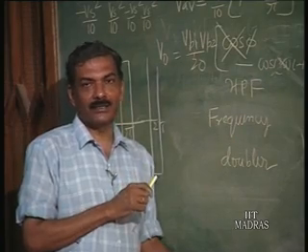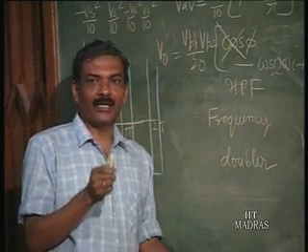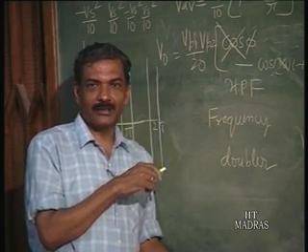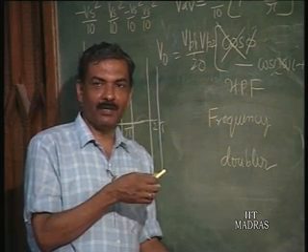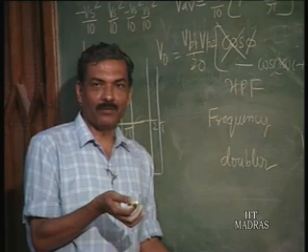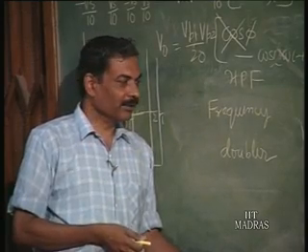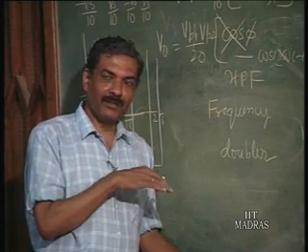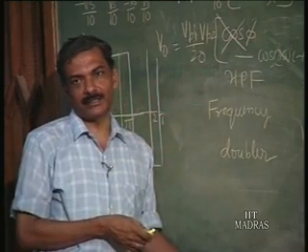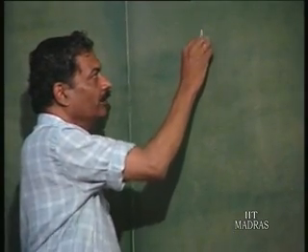If you can use it for frequency synthesis, I can get omega, 2 omega, 3 omega, etc. Then I can generate the harmonic components, and I can therefore obtain any periodic waveform using a periodic waveform as the input. A triangular waveform, for example, can be used as the input. Triangular waveform is nothing but x or t. So, using this input I can generate a sine waveform, which is going to be t minus t cubed by factorial 3, and so on. So, we can generate a periodic waveform of any shape using a triangular waveform, using this kind of frequency synthesis. Other applications of the multiplier, like how to use it as a divider.